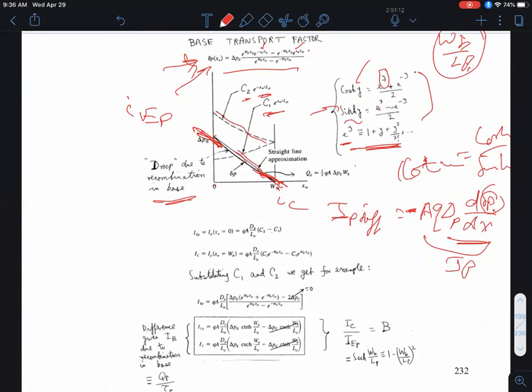All right, so if you do that exercise by taking the gradients, you end up getting these expressions over here. The important one is, once you take the derivative, you see that the LP appears in the denominator, because you have e to the power minus x over LP. Here I've still left it in terms of C1, C2. I can plug that back in over here. I'd strongly urge you to go through these algebraic steps on your own. It's very straightforward, except that the expressions look messy because unfortunately you're now dealing with growing exponential and decaying exponential terms. So you're left with all these funky hyperbolic functions, like cotangent hyperbolic, all right?